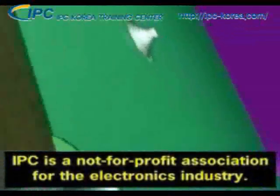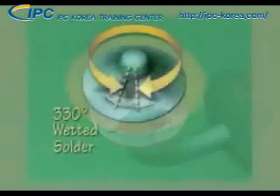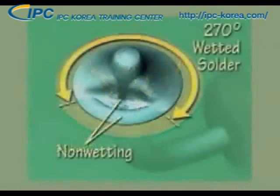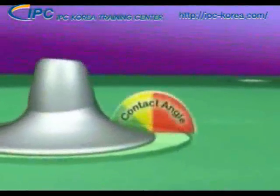Next, let's turn to the solder side of the connection. There are 3 acceptable criteria. The first is the wetting of the lead, land, and barrel. The minimum acceptable solder joint should have a concave fillet with proper wetting for 330 degrees, or approximately 90% of the way around the circumference of the lead and barrel, and a minimum of 270 degrees, or 3/4 circumferential wetting over the land. The second requirement for the solder side is contact angle.